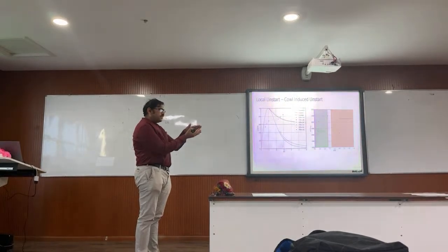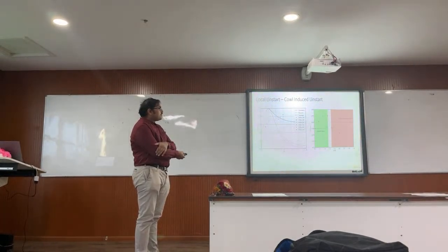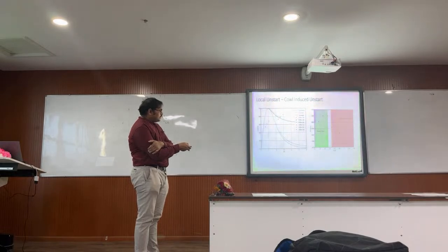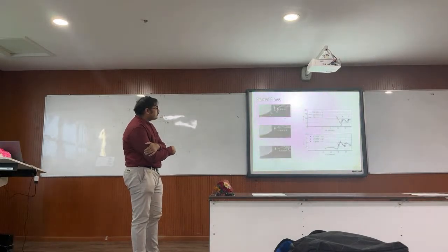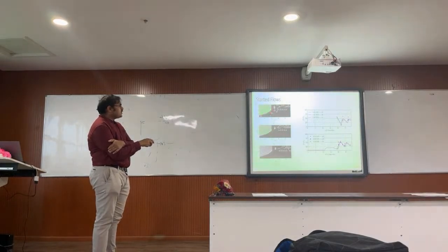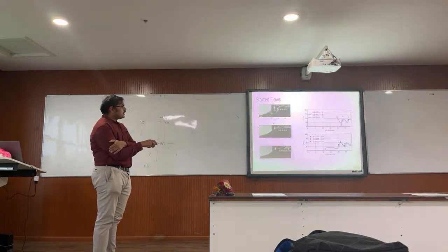Here, because we are changing the geometry, the mass flow rate actually changes. Okay. Mass capture changes a little bit. It reaches a maximum and then in the unstarted flows it drops significantly. And we can see spillage over here. So in these cases, when we change the contraction for the initial cases, it remains started, okay, and the flow features are similar as what we discussed earlier.